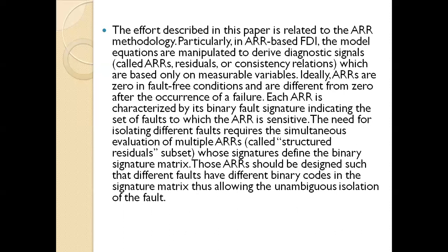The need for isolating different faults requires the simultaneous evaluation of multiple ARRs, called a structured residual subset. To define the binary signature matrix, those ARRs should be designed such that the different faults have different binary codes in the signature matrix, thus allowing the unambiguous isolation of the fault.